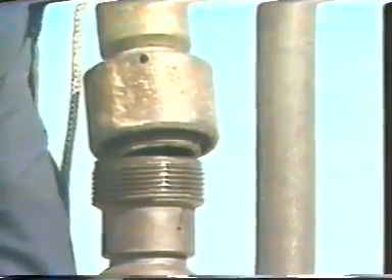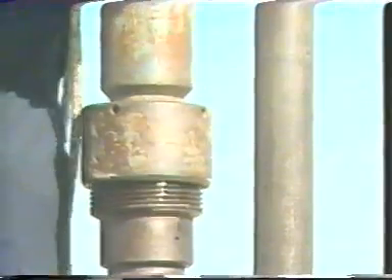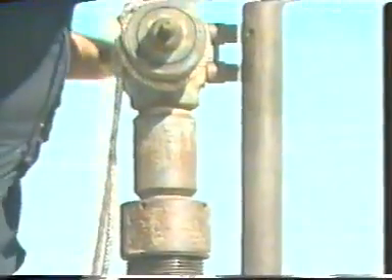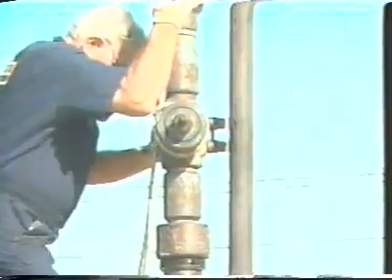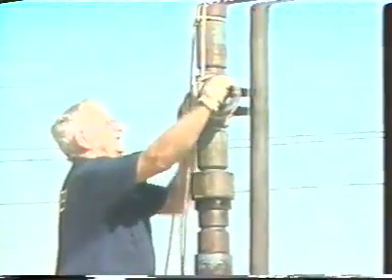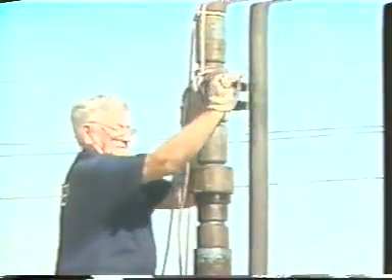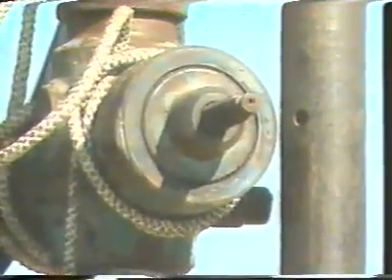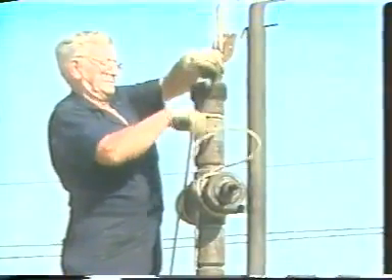With the gin pole in position, the wireline valve may be lifted and placed in position on top of the tree, where it is made up to the tree connection. If a situation should arise that requires the well to be closed at the surface while wireline is in the well, the wireline valve may be closed without damaging the wireline.